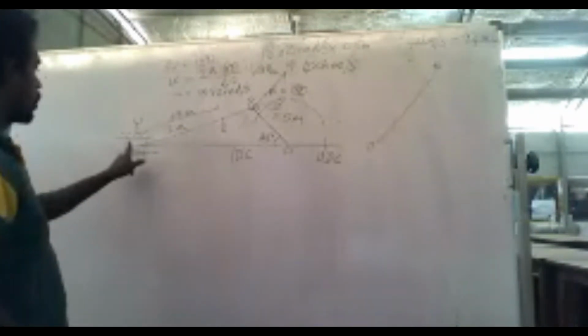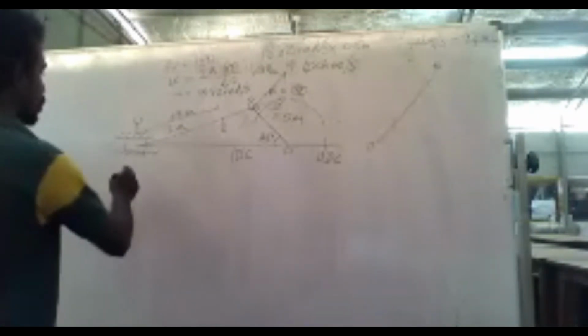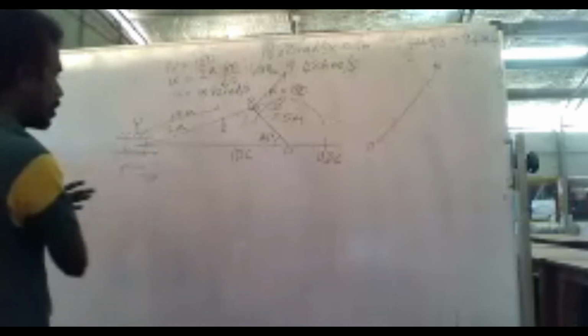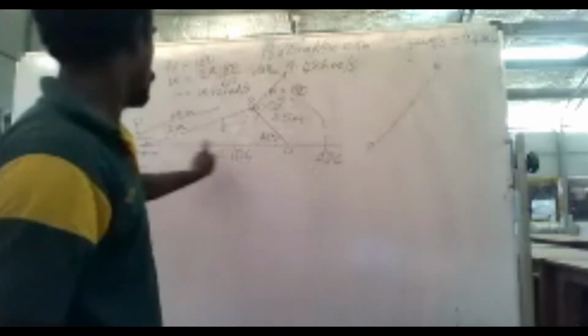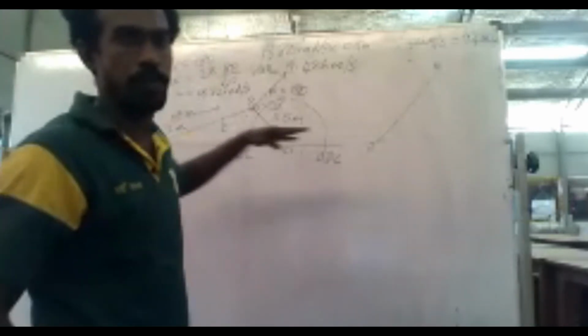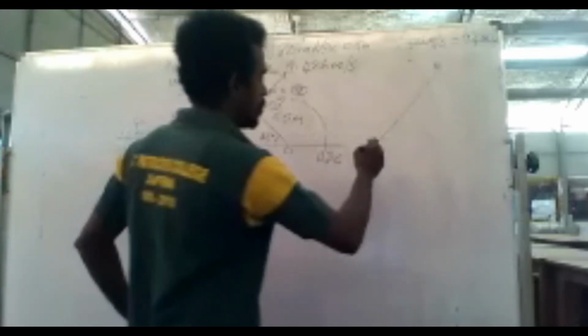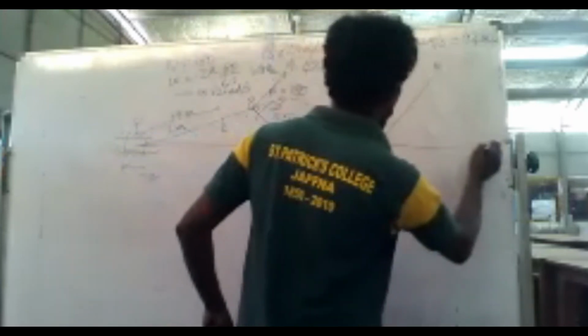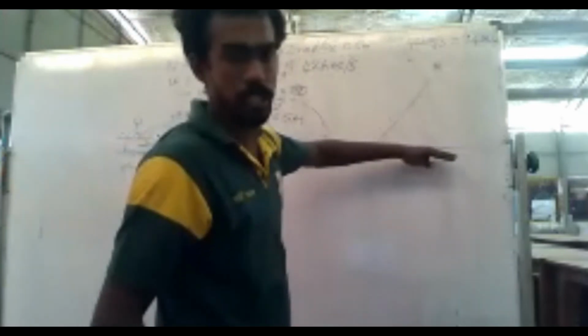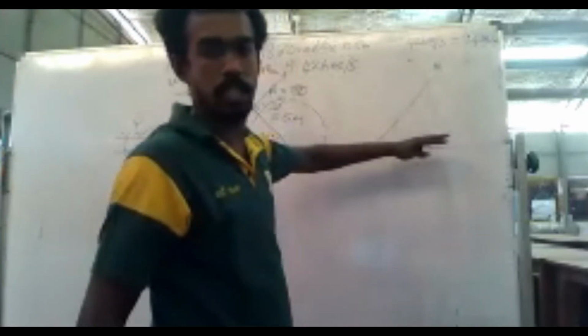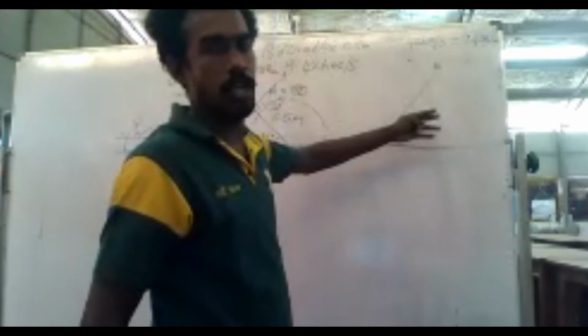What else we can do is go for the piston. We know it is going to move either this way or that way, because that's the motion of the piston, right? So that's easy for me. So I will go for that second. It is going to move only in this direction, which means I know the direction, but I don't know the magnitude.